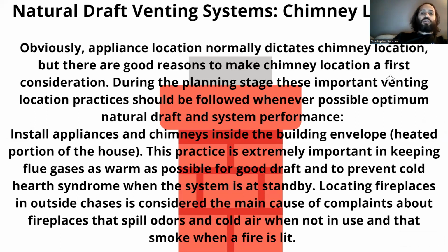performance. Install appliance and chimneys inside the building envelope, the heated portion of the house. This practice is extremely important in keeping flue gases as warm as possible for good draft and to prevent cold hearth syndrome when the system is at standby. Locating fireplaces in outside chases is considered the main cause of complaints about fireplaces that spill odors and cold air when not in use, and that smoke when a fire is lit.